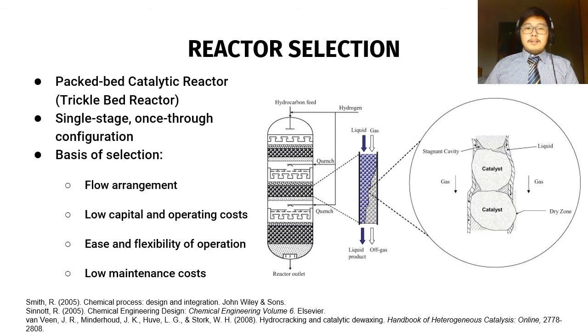This is because the liquid flow in trickle bed reactors closely resembles plug flow behavior, which would mean high conversion yields are able to be achieved. Moreover, there is ease of construction and operation since no moving parts are involved in trickle bed reactors, which also contributes to ease of maintenance and lower risk of damage to the reactor, along with lower setup costs.